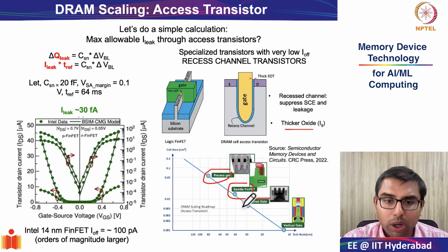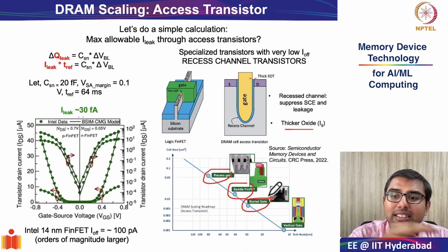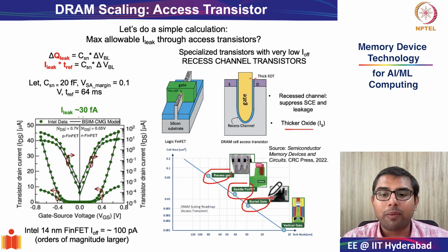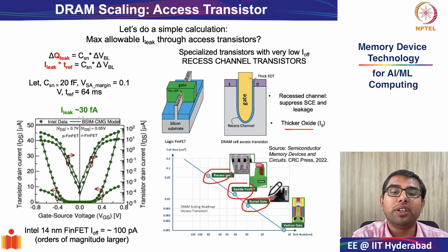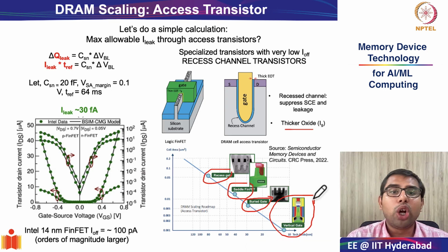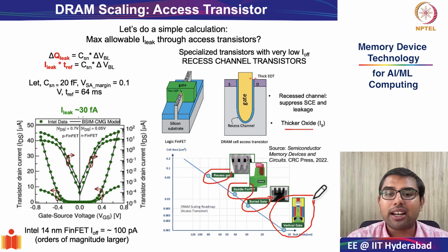Furthermore, in the 32 nanometer node, the buried gate structure was introduced to reduce the coupling between the word line, which is the gate of the access transistor, and the storage node capacitor, because the gate is buried underneath the silicon's surface. Further advancements are also happening in the form of vertical gate transistors to further improve the performance of scaled recessed channel transistors.